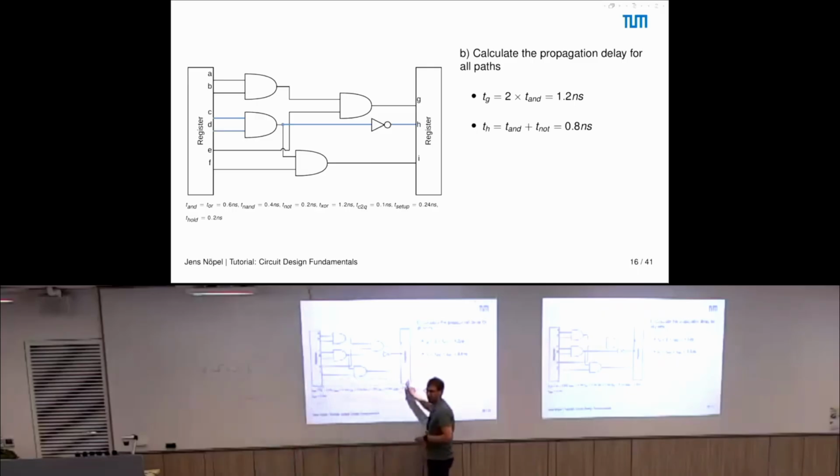And then on the second register stage, you need to make sure that the signal is stable for a certain amount of time. This is referred to as the T setup time that needs to be added here before the next rising clock edge arrives. So this is one rising clock edge here and the other one here, and this is then F clock, 1 divided by T clock.